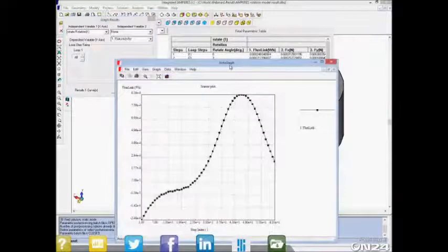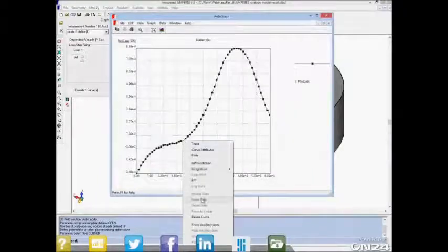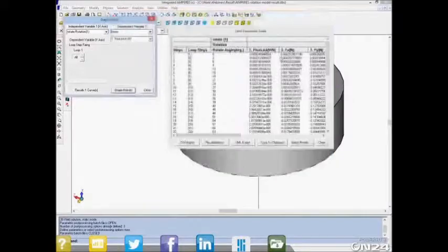We have the flux linkage versus the step index, and if I turn on auxiliary axes, that's versus angle of rotation. So the derivative of this curve will give me d flux by d angle, and then if I associate that change in angle with some amount of time, I get the voltage over that small time period.